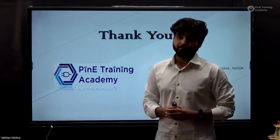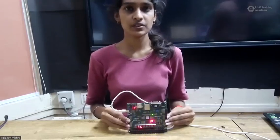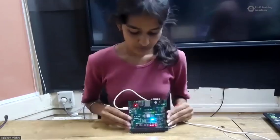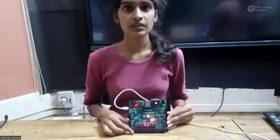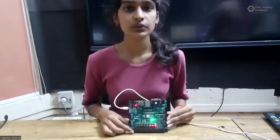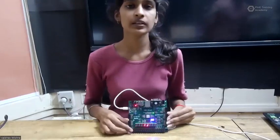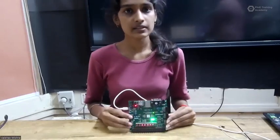Now, clearly see this output. So that is all about our project and the UART transceiver. Thank you, everyone. Now we will show you the demo of our UART transceiver project using the FPGA. Here is a Nexys A7 FPGA board in which there are a total of 16 input switches. Through these switches, we can give the input of what data we need to transmit. After we provide input to these switches, the data needs to be transmitted serially.